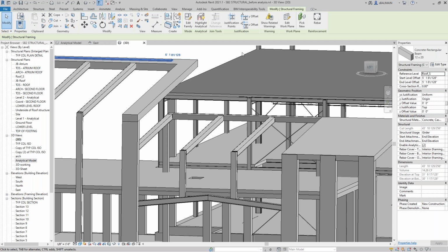In fact, if you want an element to be connected with beam and shell, you need to adapt the file. That's why we create in Revit this analytical element. But it will be the same if you go to another software, you know, because the slab and the beam are a line or a thin sheet. So if you want it to connect, it needs to adapt, so it won't respect exactly where it is.